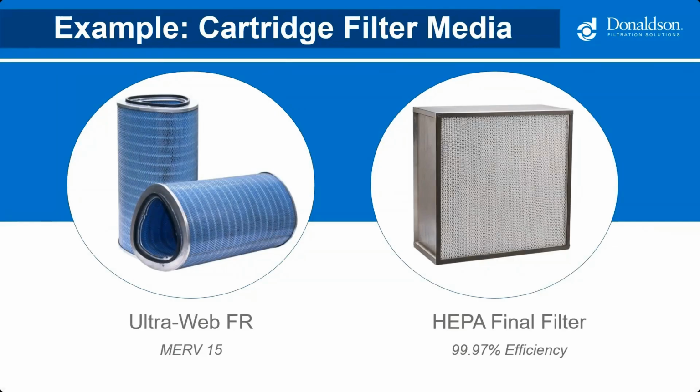And then also, as mentioned a couple slides ago, in most cases, these dust collectors are located indoors, and depending on the material being cut, the exhaust returned to the facility and the dust could be considered toxic. Such dusts include, but are not limited to, aluminum and stainless steel. In these cases, we would recommend a HEPA afterfilter, which are 99.97% efficient in capturing.